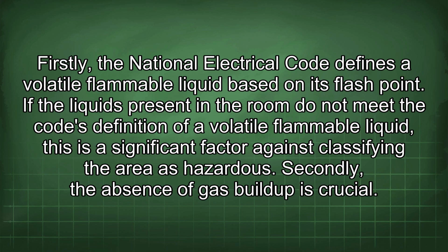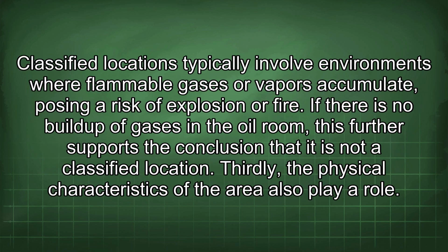Secondly, the absence of gas buildup is crucial. Classified locations typically involve environments where flammable gases or vapors accumulate, posing a risk of explosion or fire. If there is no buildup of gases in the oil room, this further supports the conclusion that it is not a classified location. Thirdly, the physical characteristics of the area also play a role.